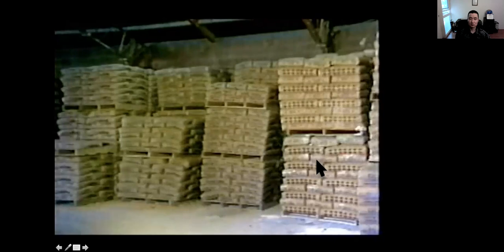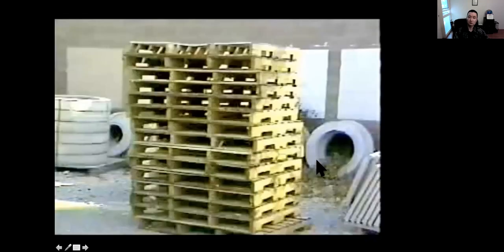Bags should be stacked close together to reduce air circulation, but should never be stacked against outside walls. Where a shed is not available, bags should be placed on raised wooden platforms at least 4 to 6 inches above the ground. Waterproof coverings should fit over the pile and extend over the edges of the platform to prevent rain from reaching the cement and platform.